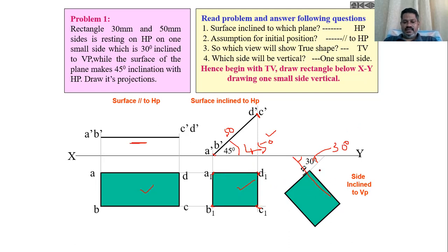Then now, take one point here on this reference line, and A1, and take the compass, get the B1 point, then get BC1, draw a straight line here, a 90 degrees line here, then BC1, then CD1, a perpendicular line, then project all these points to get the front view.